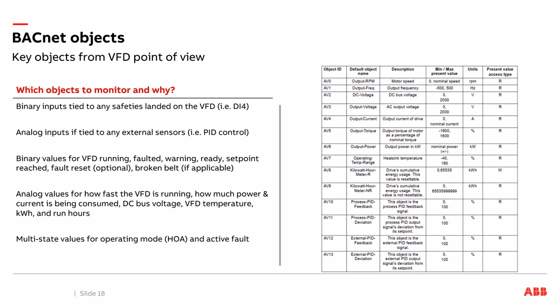So some of the most important items to look at: any binary inputs that are tied to the VFD. So I gave the example of that supply fan that might have three safeties into it. So if you've got any safeties wired to the drive, you should definitely be monitoring those binary inputs on your operator workstation and the controls.